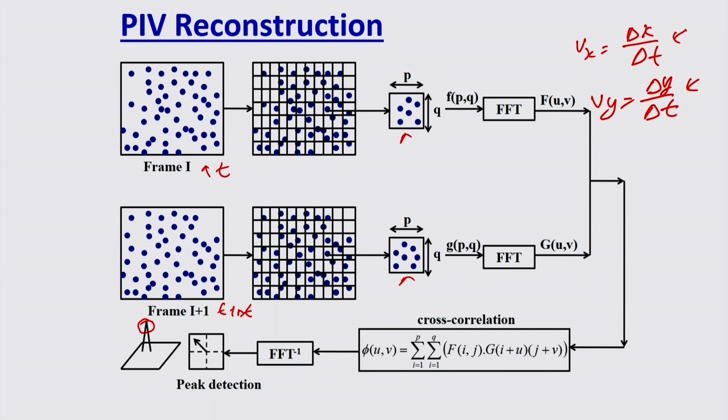This is a very good technique. It can have a very high temporal resolution, very high spatial resolution, it doesn't disturb the flow, and it can be used for many systems. But there are certain factors which affect the accuracy of the PIV experiments, and one of the factors is the laser intensity, the laser energy you are using, and the laser wavelength, because you form a sheet of the laser, your particles get illuminated because of that, and your acquisition depends on how fast your laser is generating the pulse.